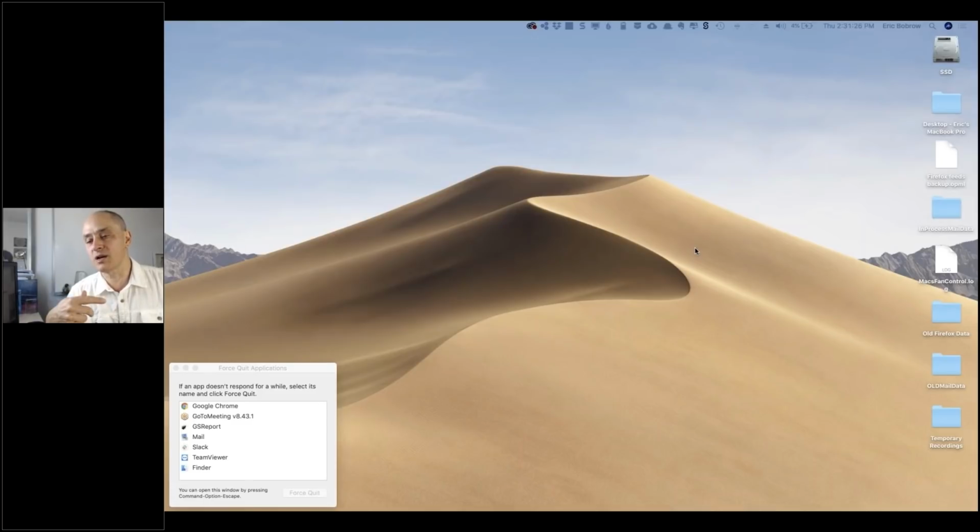So instead of just saying it's either demo or new or existing, you can say version 1 and version 2. You can have multiple renovation filters and pin an element or a module to that renovation filter, so it only shows. Those are some things you may want to explore to see if they can help you reduce the amount of duplication and having this repeated all over.